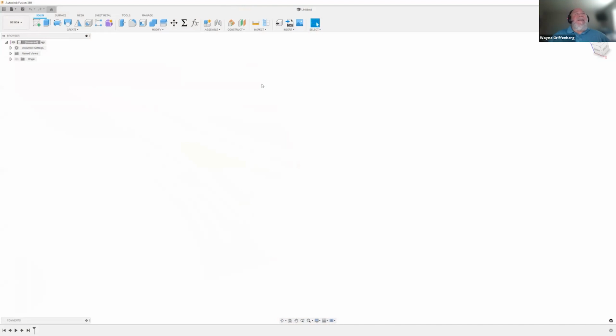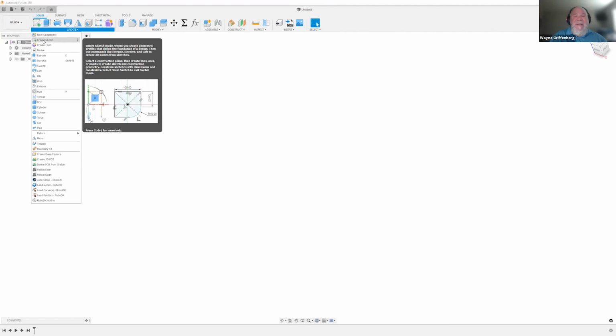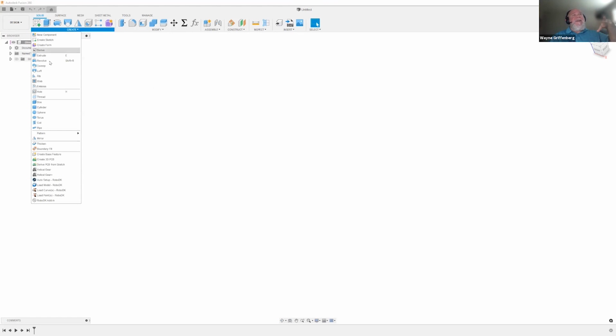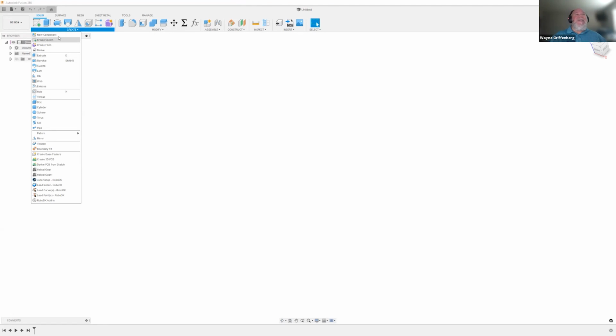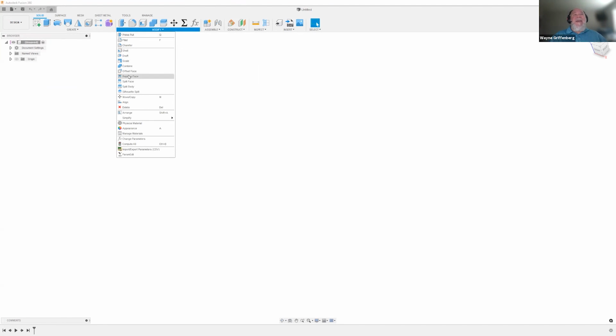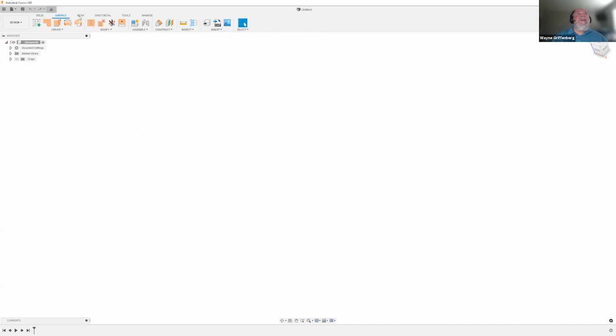So I'd like to give you a workflow of importing a part and working with that part and setting up some toolpaths and showing what that ease of use looks like. So within our design workspace, if I wanted to, I could just start to create a design, just draw a sketch on a plane and start to extrude it or revolve it or make sweeps and such, and you can make some parametric design here. Our direct editing engine, I'm going to show you a little bit more about this soon, but the capabilities of being able to do surface modeling, mesh modeling, sheet metal modeling to make those bent brackets and such, you can easily do, just simply switch from those different tabs.